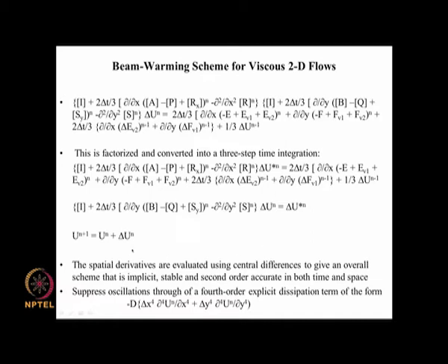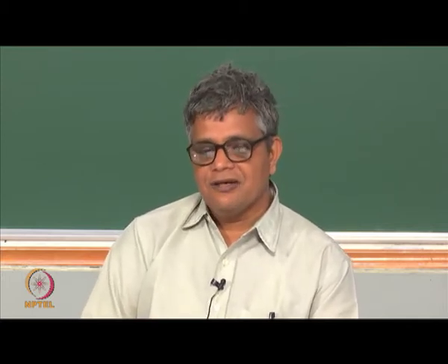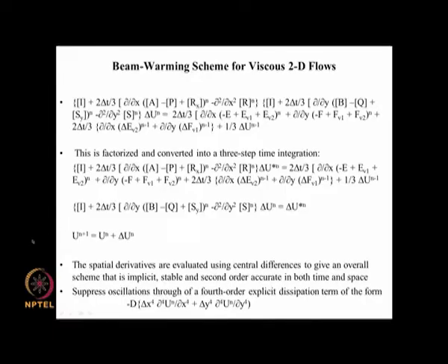So, schemes like these can give rise to oscillations, and we have seen that already for the scalar transport equation involving both advection term and diffusion term. We have seen that when we use central differences we can get oscillations, but central differences guarantee second order accuracy. So, if you want to have second order accuracy and you do not want oscillations, then we need to suppress those oscillations.